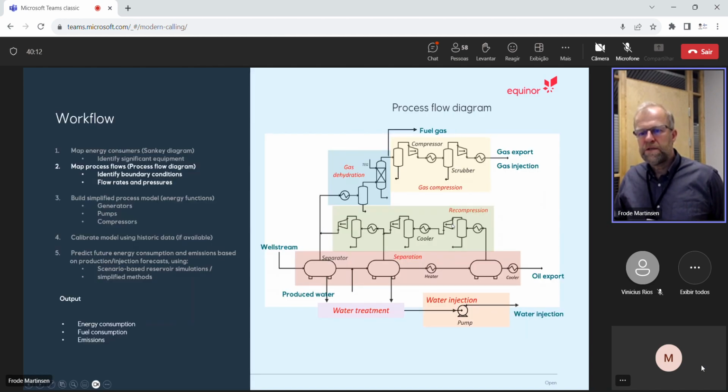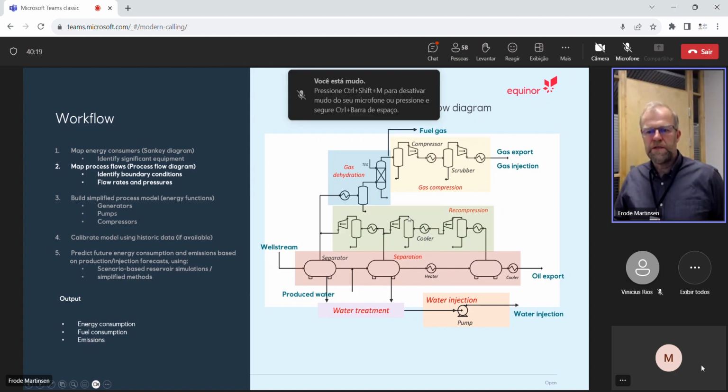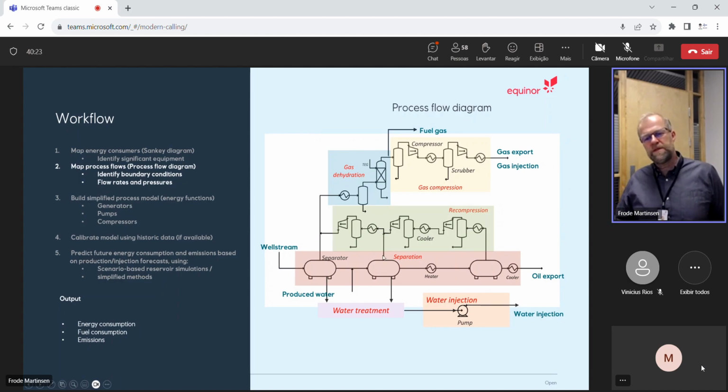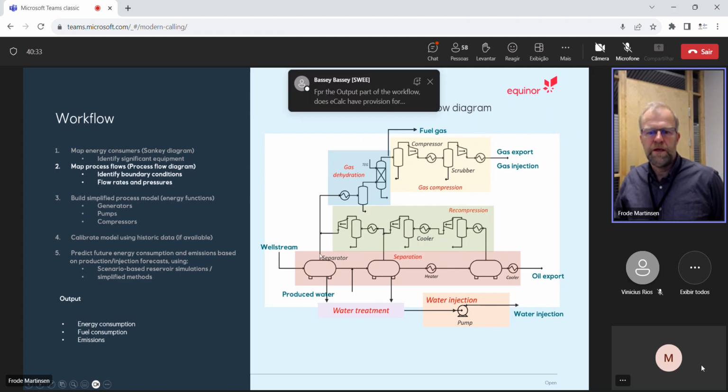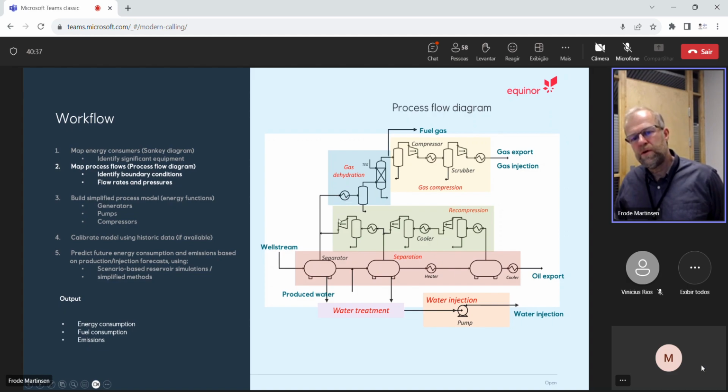And then the gas is going into a compressor, going into a new cooler, a new scrubber. Liquid is collected. Gas is then compressed up to this here. Now it's at 7 bars. Now you can mix it with this gas. That gas is cooled, scrubber, you take off the liquid again back here. This gas is now at 15 bars, you can mix it with this gas. Then you put that gas into another cooler. This is where the main gas rate is, of course. The inlet separator is where you take off most of the gas.